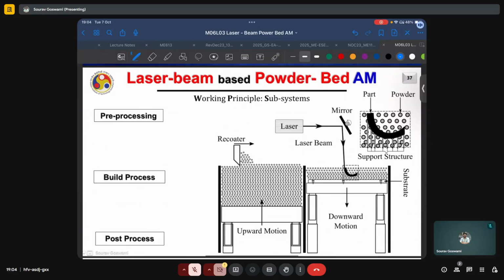Also, say, loading of powder, loading and clamping of the build plate, cleaning of the machine, changing of process parameters, or say in the case of powder bed fusion, even there might be multiple laser spot sizes available, then choosing the specific parameter space.